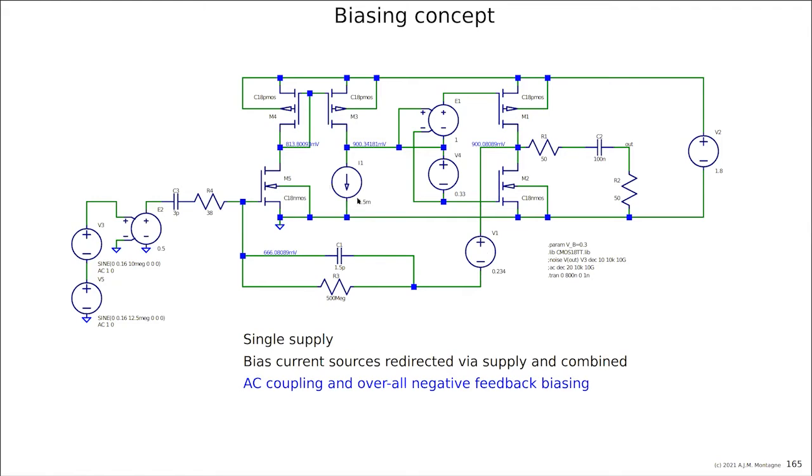And then you see if this is the same noise as M5, then probably the current noise of M5 will be doubled if this transistor is exactly the same transistor, having the same gm and the same current. So that's why the noise needs margin, and maybe we already know that this must be made in a smarter way than just putting some transistor there without thinking too much about it.